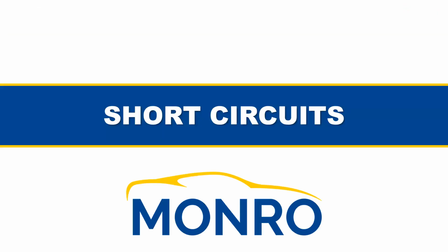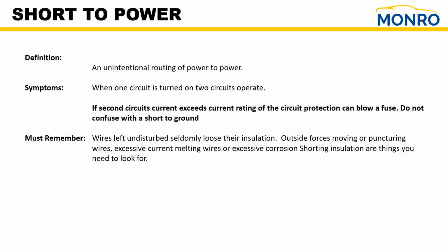So we talked about short circuits as they relate to a short to ground, but now let's talk about the short to power. By definition, it's simply an unintentional routing of power to power. The symptom is frequently that when one circuit is turned on, two circuits begin to operate. If the second circuit exceeds the current rating of the circuit protection, it can blow a fuse. So don't confuse this with a short to ground. And we have to remember that wires left undisturbed seldom lose their insulation. Outside forces moving or puncturing wires, excessive current melting wires, or excessive corrosion are things you need to be looking for.